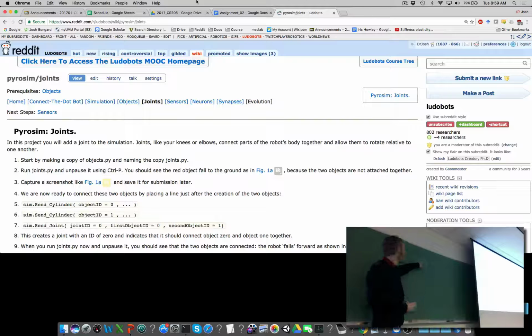So it's got the same radius as these two objects, but it's got zero length. So if you run this, you shouldn't see anything other than two cylinders, right? So we've hidden a third cylinder inside the intersection between cylinder 1 and cylinder 2. I can then create a joint that attaches C1 to C3, and I can place the joint there.